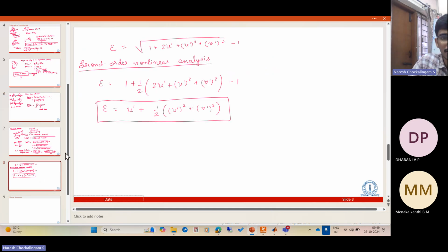If you recall, the force F is acting on the current configuration. You're perturbing that configuration by some delta U, and this force is doing work on that change. Similarly, the sigma will do some work on the change in that strain.